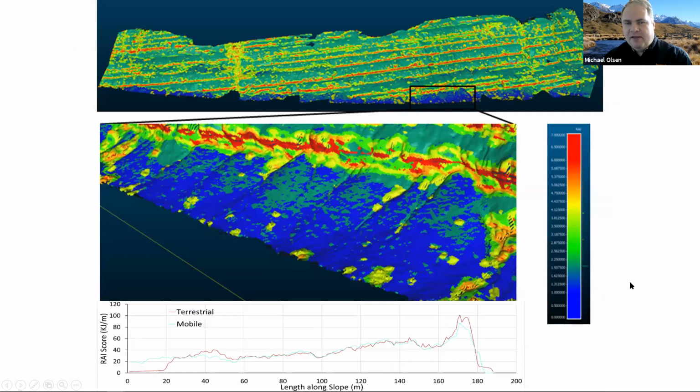When we go through and apply the flow chart, we can classify the slopes. This is a slope in Oregon in Eddyville along a new highway realignment that was opened up a few years ago. We can then color code it based off the different observations. The dark blue is talus deposits down at the base, the red are the overhanging sections, and the light green is what's classified as intact rock.